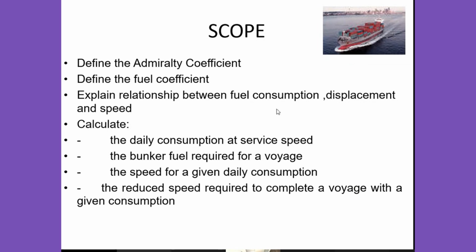With some unpumpable on board, as we know, every ship has some unpumpable, the bottom oil which is hard to pump. So maybe 5 tons or 4 tons or 7 tons, whatever it is, based on the number of tanks. That means that particular oil I cannot use. So ROB minus the unpumpable is the effective fuel I have, and on the basis of that I can calculate the speed at which I should go so that I can make the port with the unpumpable still intact.